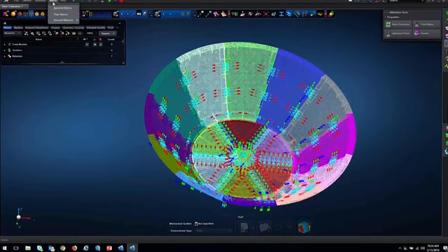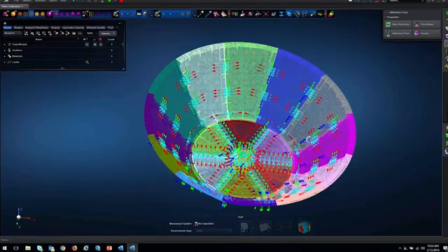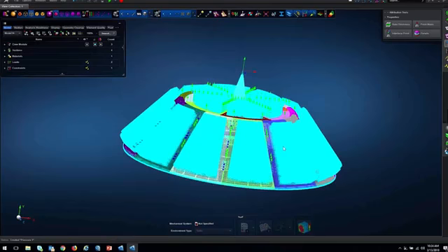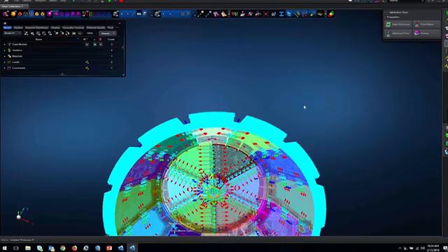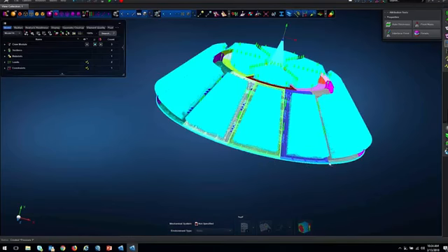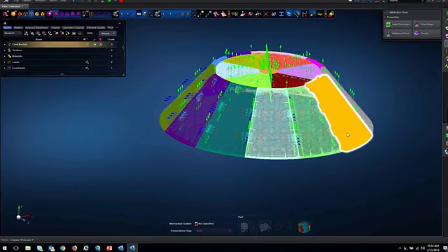And lastly, I'm going to run one more script through which we are going to create the loads and boundary conditions applied to this model. Basically, there is a remote load applied onto the structure, maybe like a concentrated load, and an internal pressure load is applied on all the panels, and the bottom structure is constrained, as if it is connected to the rest of the structure in this case. So that is how the model is built using a couple of scripts.